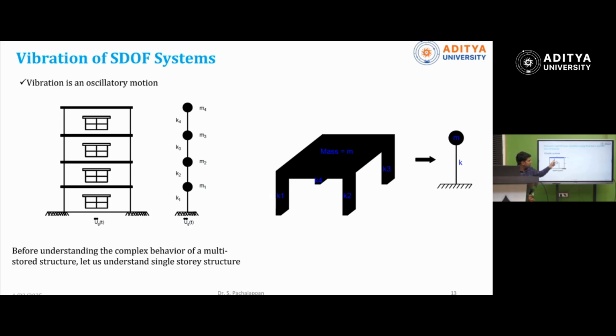Then the arrangement which you are seeing here is called a damper. Generally, different types of dampers are there. Viscous damping, structural damping, fluid damping, radiation damping. Generally, in structures, the damping force is represented as a fluid viscous damper. This container is called a dashpot. A dashpot is a mechanical device filled with oil or a highly viscous fluid, which is going to control the displacement.